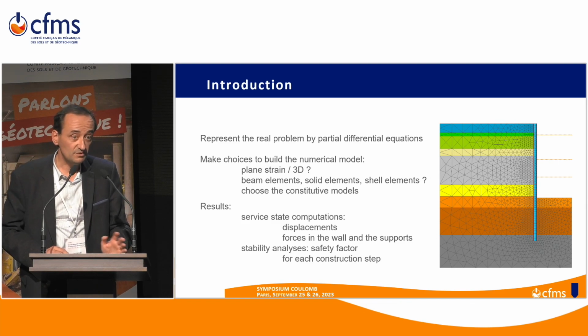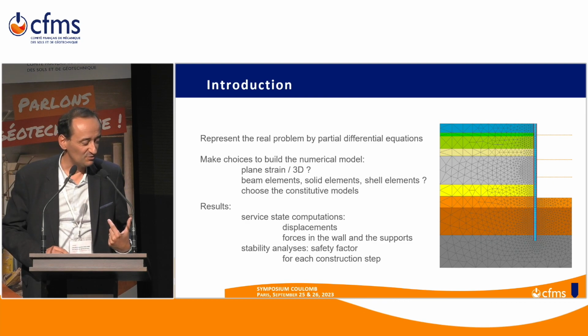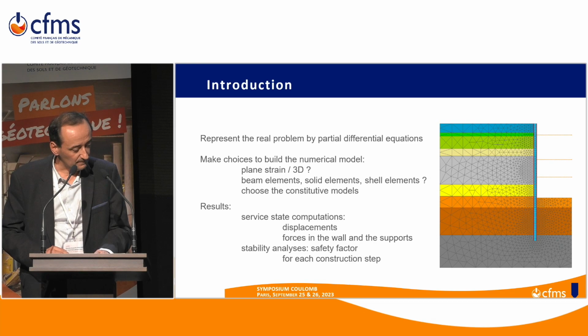You have to make other choices that are more numerical ones between types of finite elements. For the wall, for instance, you can choose between beam elements or solid elements. And also you have to choose a constitutive model. And since I've mentioned we are dealing with elastoplasticity, we have to pay special attention to the type of model.